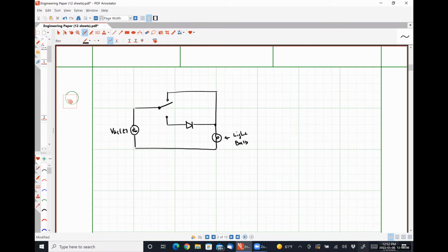So anyway, the hotter the filament is, the more light is emitted. And although the voltage is constantly changing polarity back and forth, and at some points the voltage is zero, it's never enough, or it's happening so rapidly, that the light bulb never has a chance to cool down enough for the light to turn off, okay? So for this diode path here, we're going to see effectively the same thing. We're never going to have enough time for it to cool down, even though there's going to be a small period of time where there's not any voltage being supplied, right?